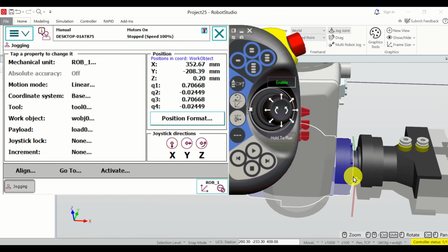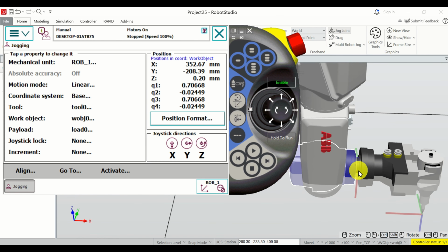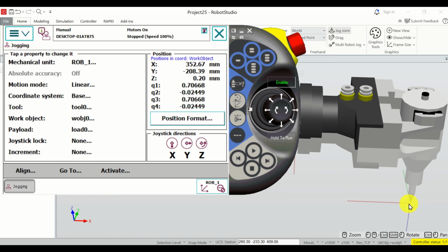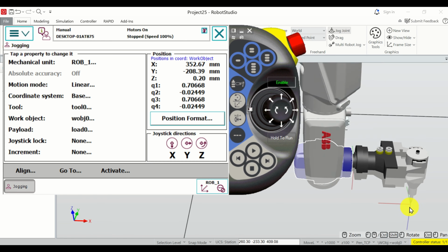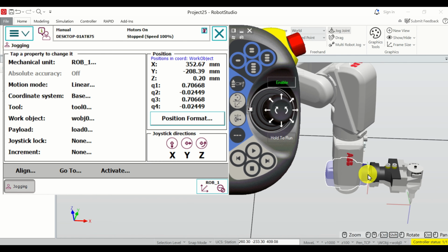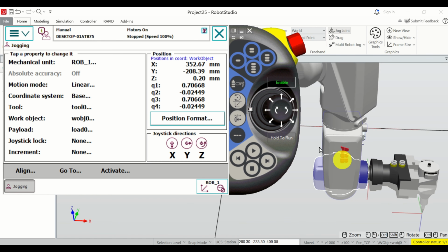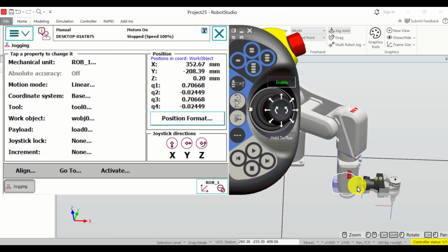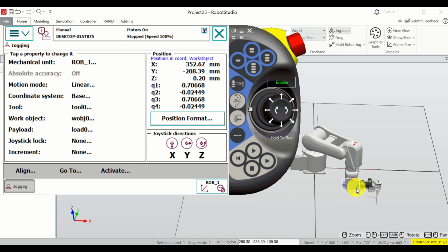And you can clearly see that the center reached almost 0. However, the center of this coordinate system is below our plane. This means that we are actually tracking the center of this coordinate system, and these coordinates are actually the coordinates of this point. And this is how you can experimentally determine what you're actually tracking. Of course, over here you're going to crash the robot, and you shouldn't do this. However, you can always measure the offset or do something similar.